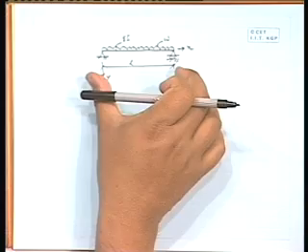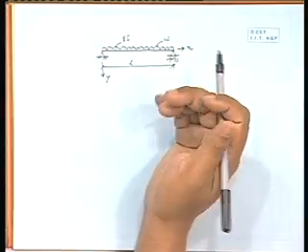Now, if we start from this end or the other end, both the side supports are there. So, we have to know the value of those reactions. In the earlier case, the support was on the left side and one free end was there, we were trying to proceed from the free end, so we need not bother how much will be the reaction at the supports. But here we can start from this end or other end, both ends are supported. So, first job is you have to find out the reaction, and that will be utilized for finding out the bending moment expression, and that will go to the differential equation.